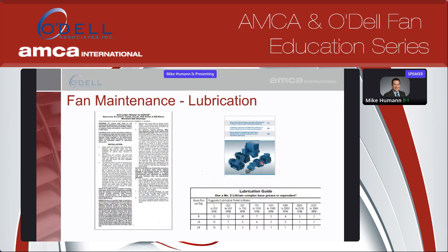A good way to do that is to use the fan manufacturer's installation and maintenance manual. It's a good tool, but bearing manufacturers have their own as well, and so do motor manufacturers. Most fans use a lithium complex grease, so that's something you definitely want to be aware of. Most motors actually use a polyurea grease. Those two greases are not compatible with each other. So it's something you certainly want to make a note of.